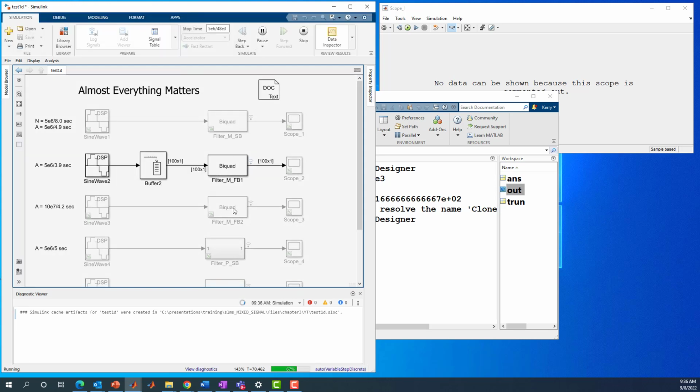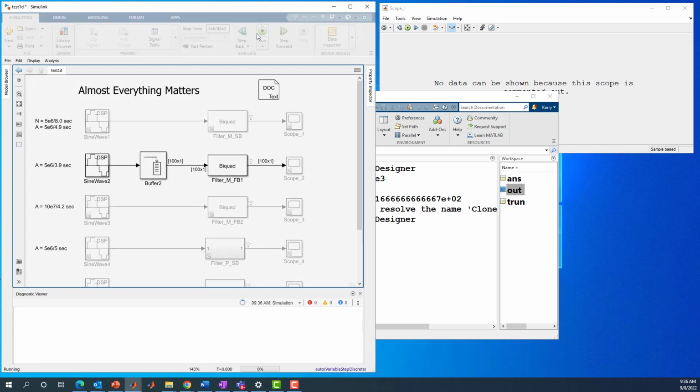And it is in frame-based mode, and it is indeed faster. So one of the benefits of running in frame-based mode should be, or is hopefully, acceleration of your simulation. Again, we're amortizing that overhead over a frame as opposed to each sample. We got about 4.2 seconds on that run, or 4.3. We could, again, run this a number of times when you're doing benchmarking. Typically, you want to do it a number of times there.